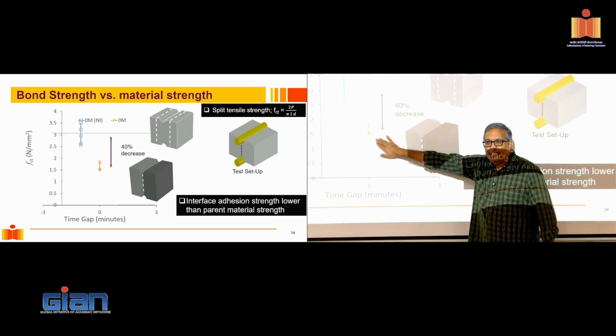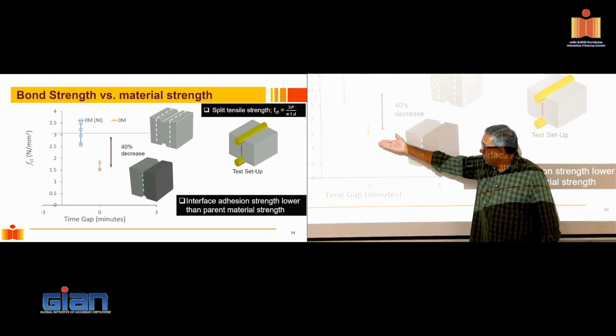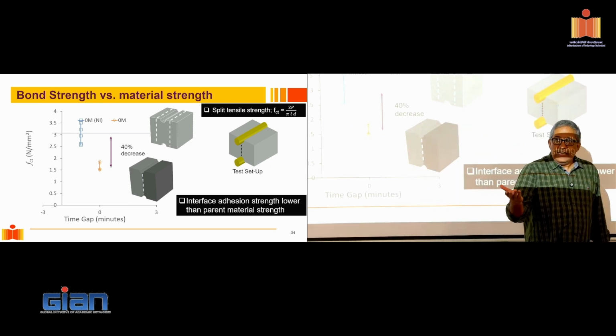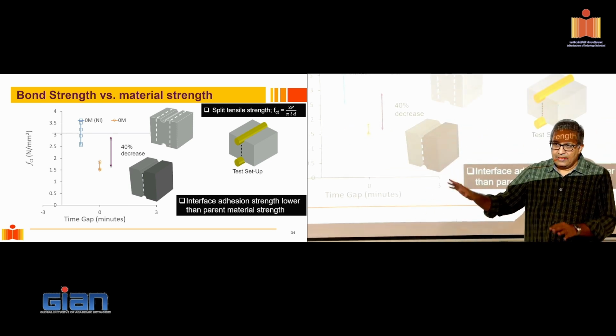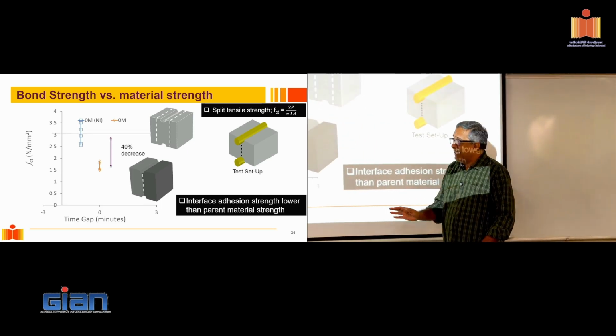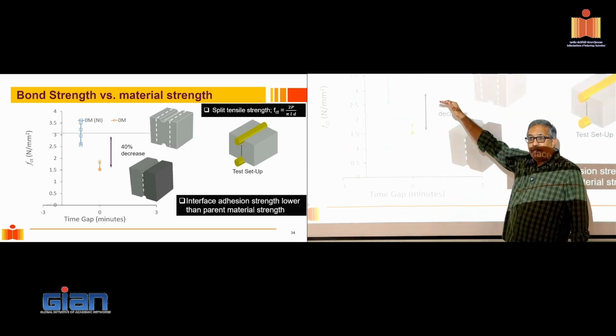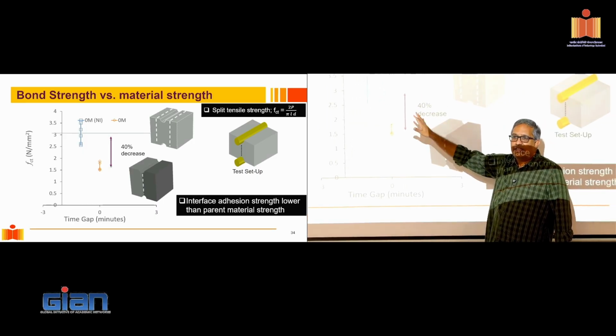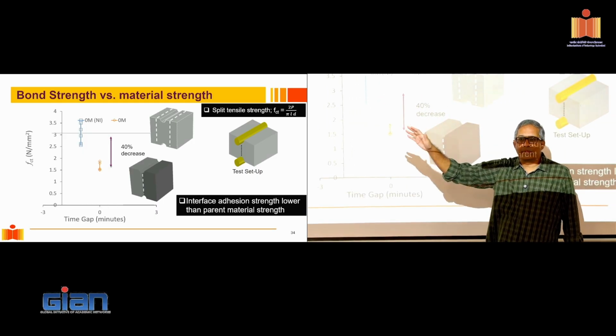If I try to split the interface, the strength is abysmally low. It's about 1.75 or so. So now, if I want to continue using it, treating it as if it's 30 MPa in all directions, the first thing I have to do is to translate that and come up with a new relationship that gives me the tensile strength, which is not your 7.5 square root of FCK.